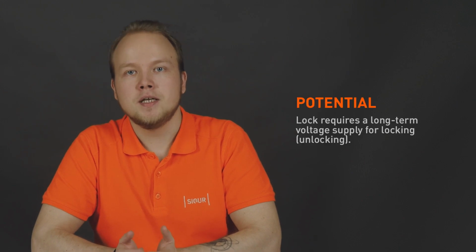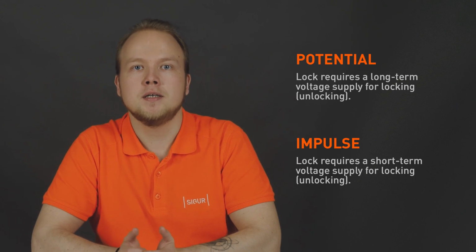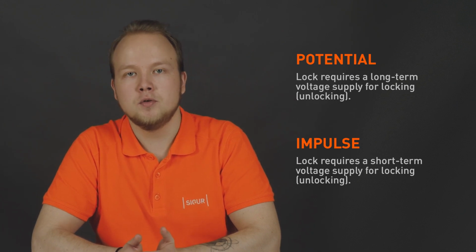Now let's go back to discussing locks. They can be electromagnetic, electromechanical, shift, solenoid, and electric motor types of structures. In addition, the security systems market is also widely represented by various locks. Each of the listed types can be divided into 2 groups based on control type. Potential, when the lock requires a long-term power supply for unlocking or locking, and pulse, when the lock needs a short-term voltage supply to open or close.